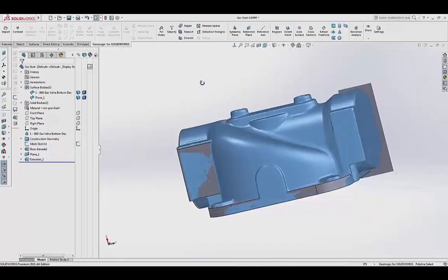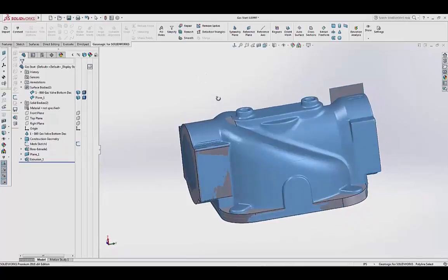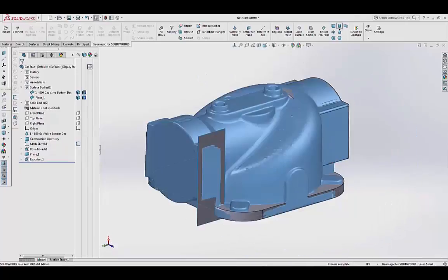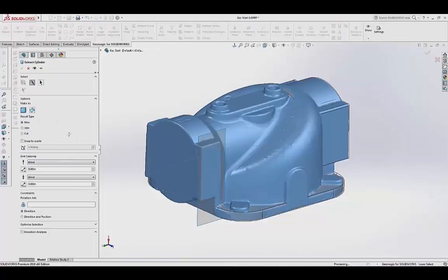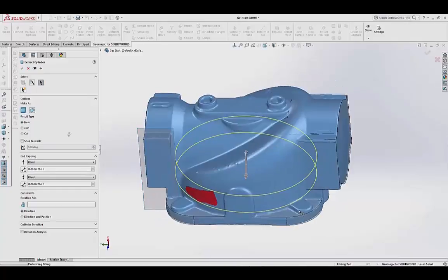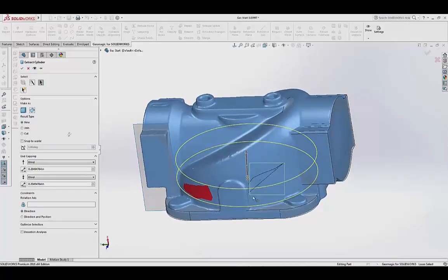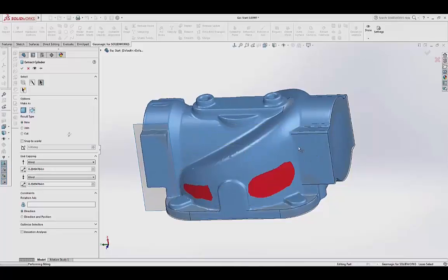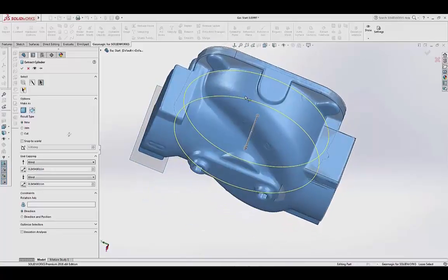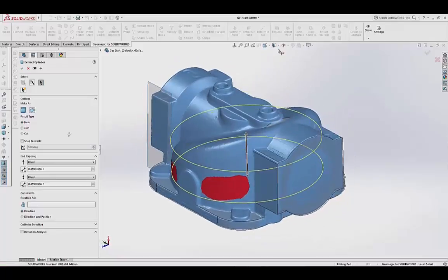And then once I hit OK, you see here that it creates that solid in space directly over top of the polygon. You can see I can also do cylinders. So if I want to take this cylinder here and create a manual selection all the way around the outside, you see I can select these four different areas, and as I do it, it gives me a preview of what that cylinder is going to be, so I can keep adding data and let it recalculate.